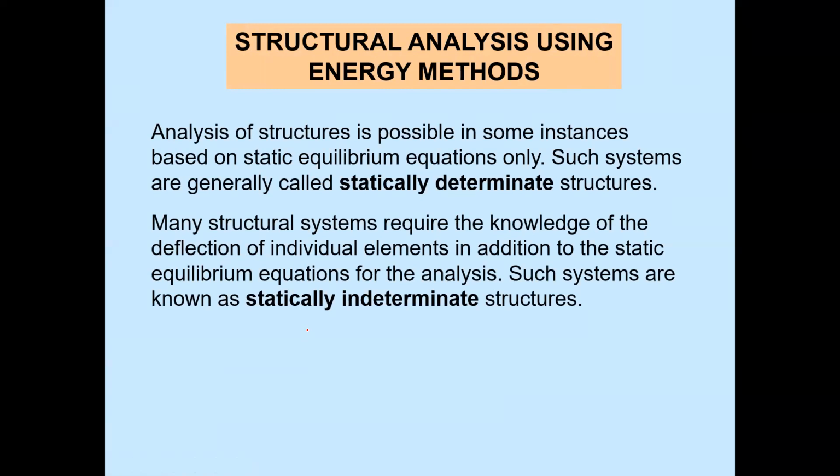Energy methods are generally used when there are statically indeterminate structures, because determinate structures can be easily solved by the force equilibrium conditions as well as the compatibility equations. But when there are statically indeterminate structures, then we need the energy methods. By using these energy methods, we integrate our equations and find a solution.